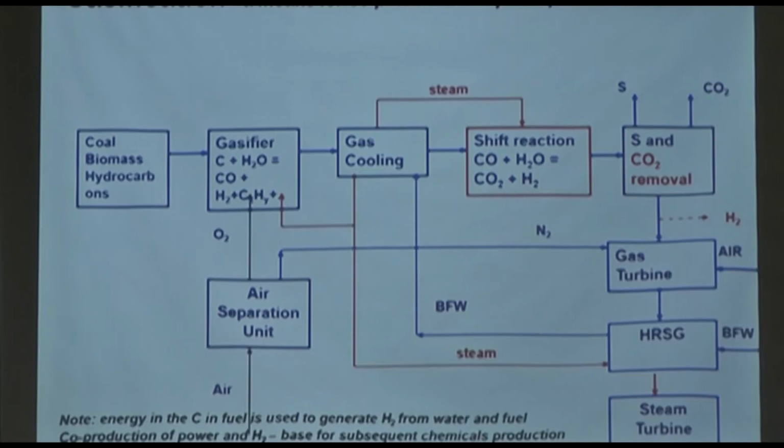Sorry, which gases? Not SOx. Because it is substoichiometric oxygen, sulfur dioxide will not be present, but sulfur has to go somewhere. Sulfur goes in the form of hydrogen sulfide, H2S. But that is not bad, because you can capture the hydrogen sulfide later on and get elemental sulfur through the Claus reactors, which you can sell.